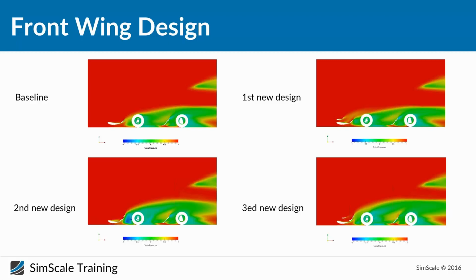Yeah, I mean the separation at the top of a wing element in this case is not necessarily significant in terms of an issue. You want the flow to be clean, but it's not always a problem if you've got some small separation at the top.